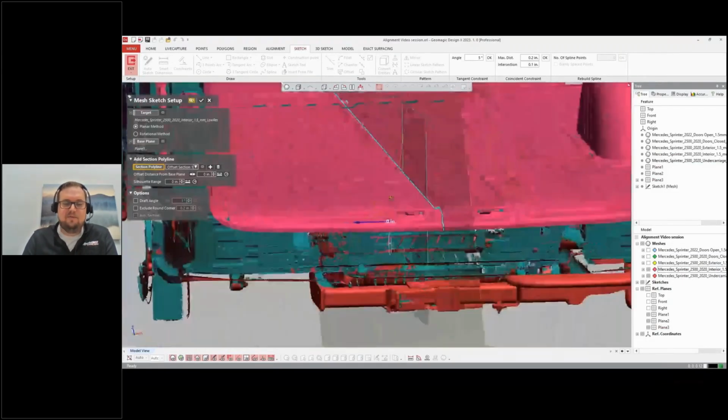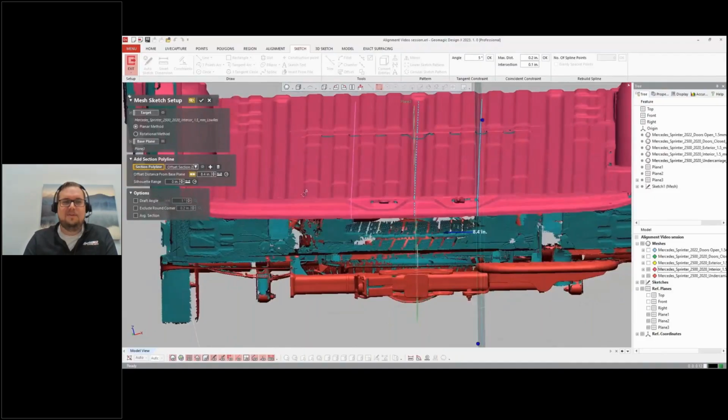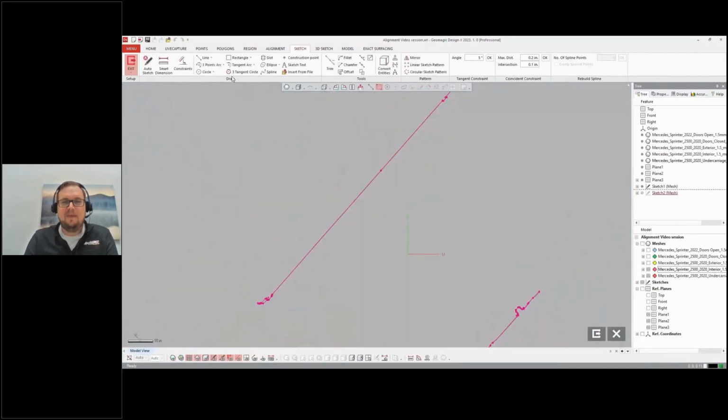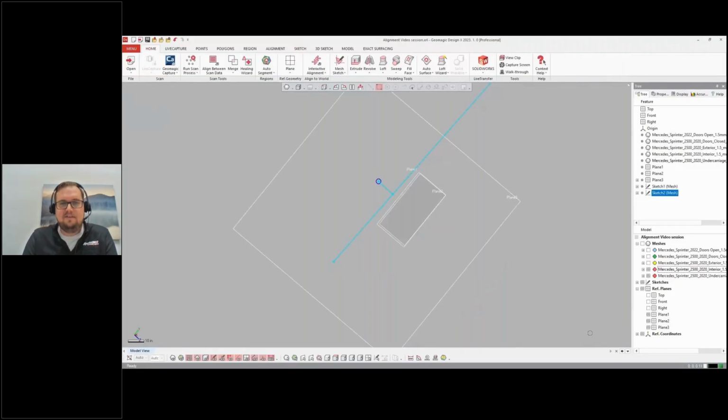We don't have to rely on eyeballing a mesh into place, or dialing in measurements one click at a time, or typing in measurements and remeasuring and checking. We're able to extract this very accurately and essentially get all we need to create a very solid XYZ alignment here, again, without that manual interaction. I'm just doing a quick crosshair here to give me a location for my origin and an axis.